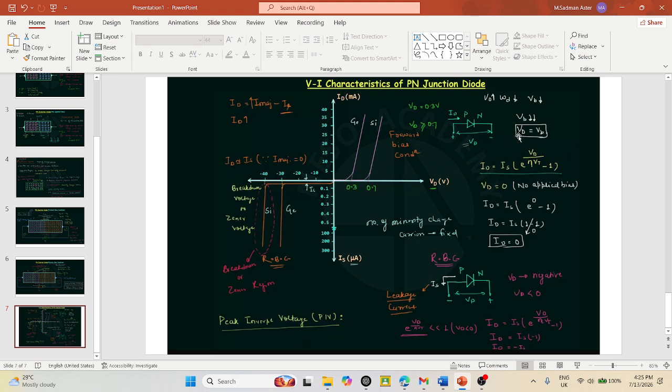Whenever our applied voltage is equal to the potential barrier, we will see a small rise in current through the PN junction diode. Whenever our applied external forward bias potential exceeds the barrier potential, a discrete flow of current passes through the PN junction, and we see a sudden rise of current in the graph.